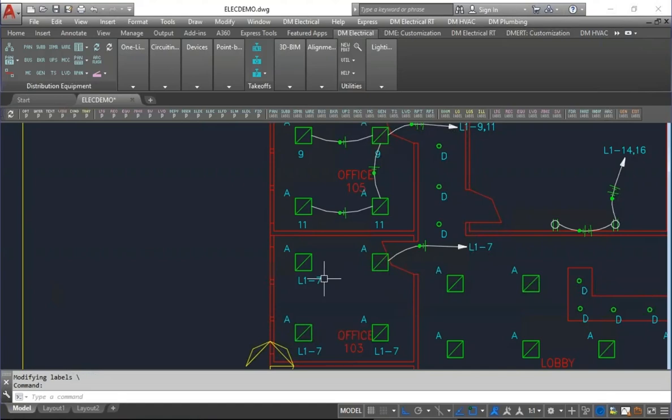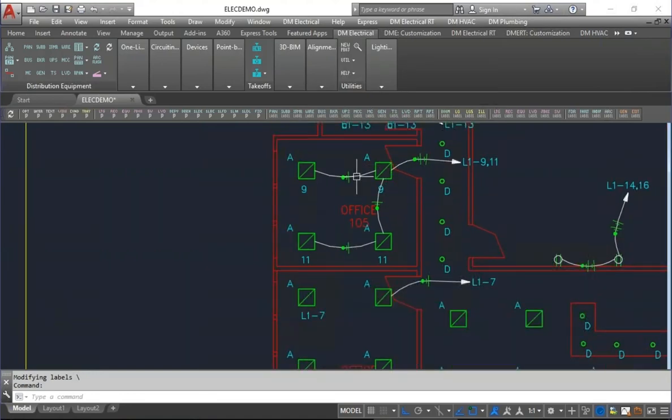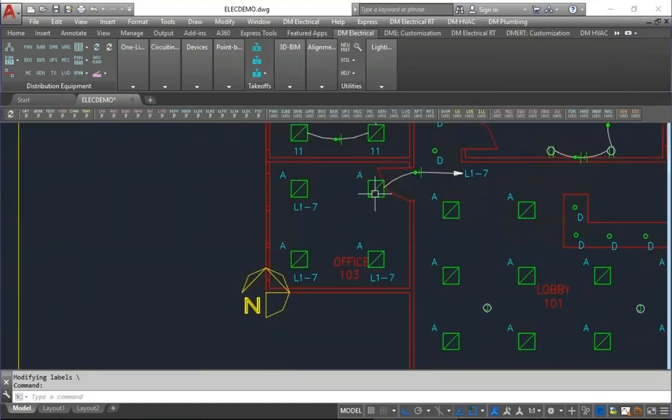Currently, our voltage drop depends on these loops being inserted because we actually trace the path of the loops and we calculate the voltage drop using that to calculate distances. And as you move along, you're going farther, but there's less load. We take all that into account when doing a branch circuit voltage drop. If you don't have the loops, we don't know the path, and so we can't calculate the voltage drop.